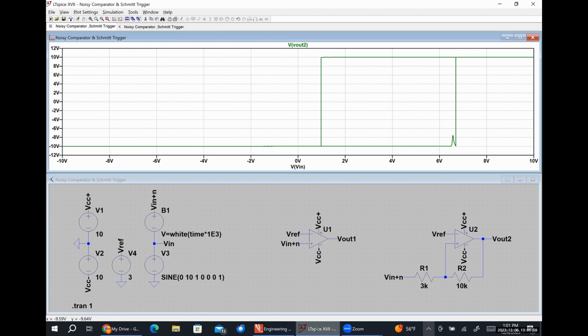No, that's how the math works. We are assuming that there isn't a little bit of range, is effectively what's going on here. So we made some significant assumptions here. R1 and R2 were significantly smaller than Rn, so that we can say that there is no current flowing through that. No current flowing through that makes our reference voltage equal to V plus. We've made some assumptions here that are allowing us to get to a single number, but the single number agrees with our simulation.